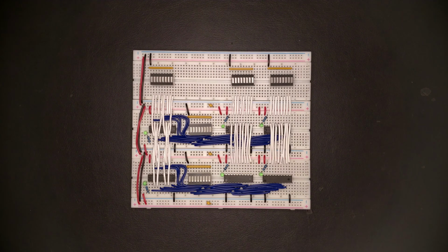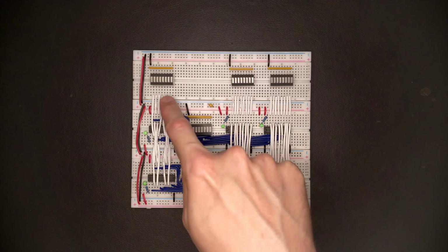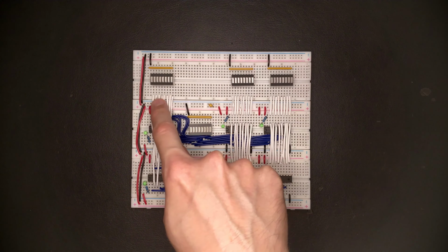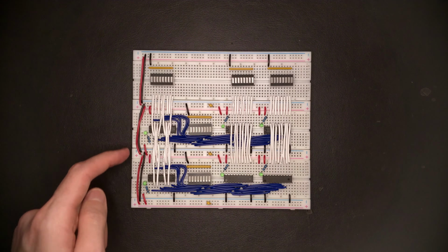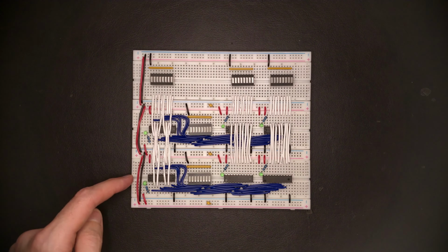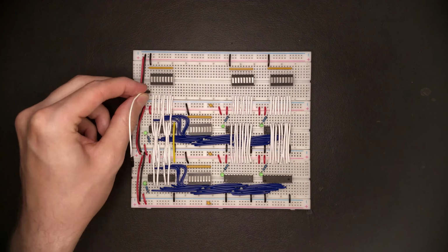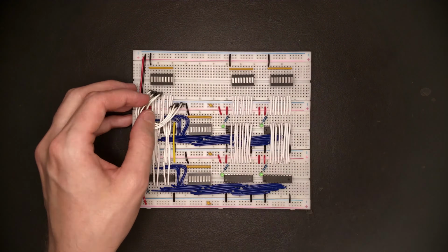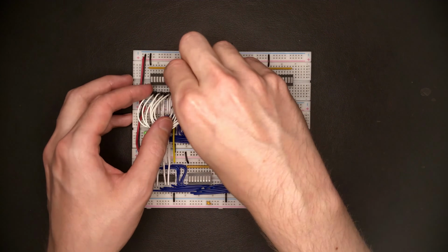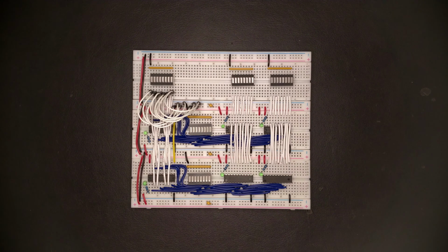And now what we should be able to do is wire up the write data input here to a pattern like we had before, maybe alternating ones and zeros, and then store that pattern into one of these registers by selecting the corresponding clock enable input. Speaking of the clock, that's something we also want to hook up. And then let me set up a pattern. And now we need control lines for the write enable inputs and the output enable inputs.